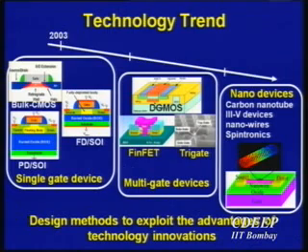So if I look at the technology trend, in order to deal with some of these effects, researchers have been looking at different kinds of devices. The kind of device we've been looking at today is mostly a single gate device. Bulk CMOS is an example of that. But as you have seen, and I mentioned earlier, even today's bulk devices really do have lots of patches. Patches meaning, okay, halo doping here to take care of certain other effects. For example, you might have to replace your thin oxide with a high-K material and so on. Those are the kinds of things that one has to do, and people have started doing them in today's nanoscale technology.